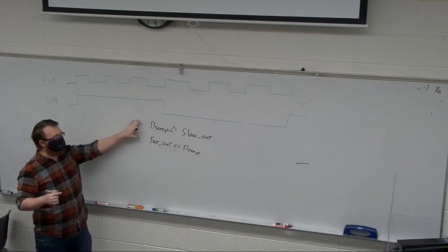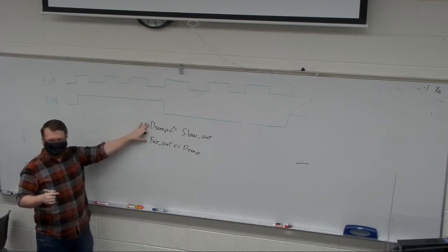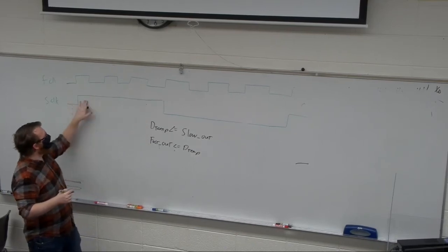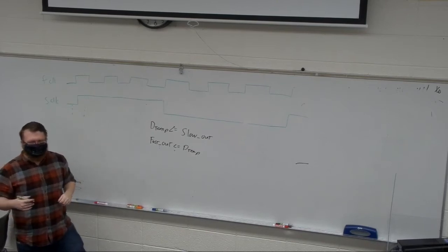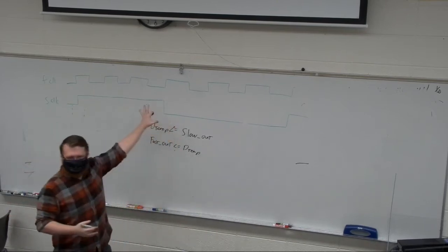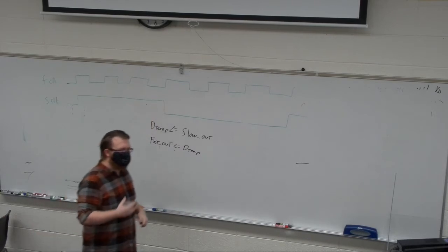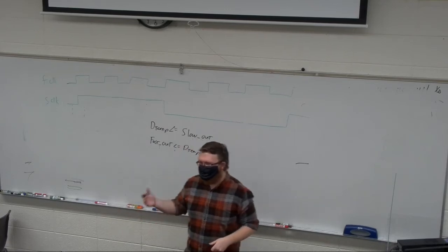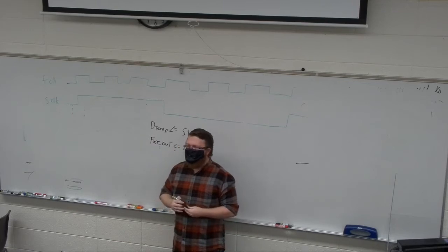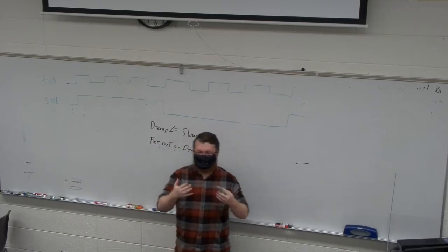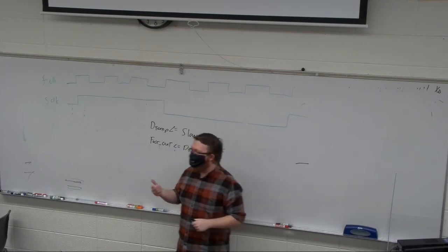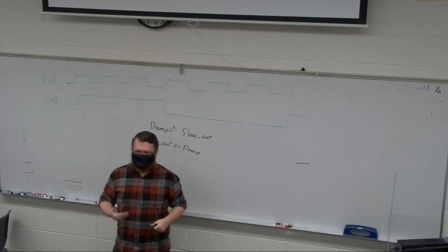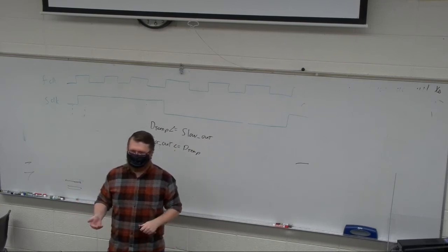That's the implementation of slow to fast. And then fast to slow is just counting. Now we're not going to have to worry about that because these are okay solutions for one-offs. But realistically, we want to be concerned about major data paths, right? When I start pushing in tons of data over and over and over again, we introduce this concept that I keep mentioning called the FIFO. And you have 2 different types of FIFO that serve different functions, but they're both incredibly useful. You have synchronous FIFOs and asynchronous FIFOs.